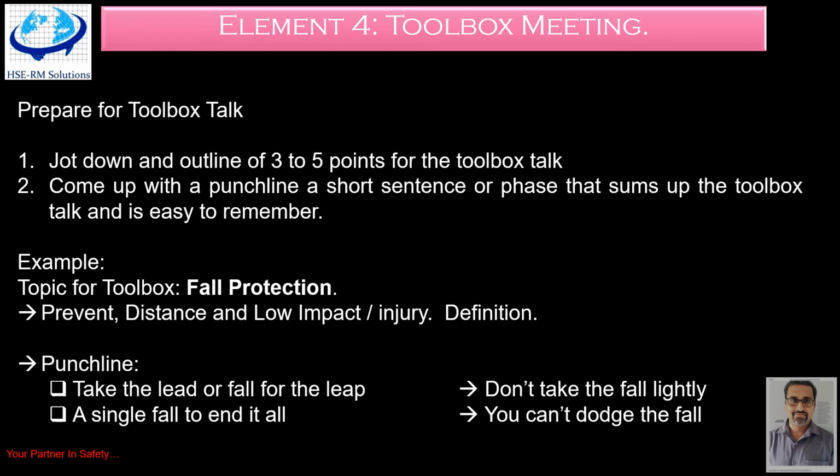Whenever you're working on any temporary platform, if you don't anchor yourself to the structure, either the structure will collapse, or the thing that you have built will collapse, right? So you have to first understand which is more stable. Always anchor yourself to a stable surface. If not, then you should have a lifeline, and you have to anchor yourself to a lifeline. The last resort is to anchor yourself to the existing structure or any temporary structure that you have built up. Correct? So this is very important to explain.